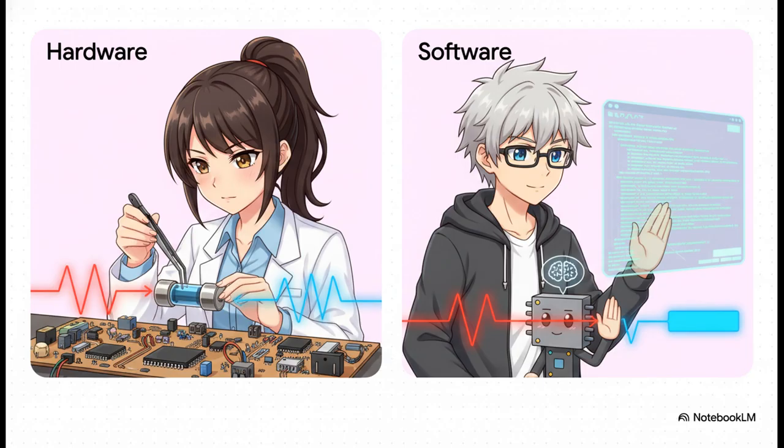The software approach is different. It's less about fixing the signal and more about teaching the microcontroller's brain to just be a little more patient. The code essentially says, hey, I know you see a bunch of signals coming in, but just pay attention to the first one and ignore everything else for a few milliseconds.